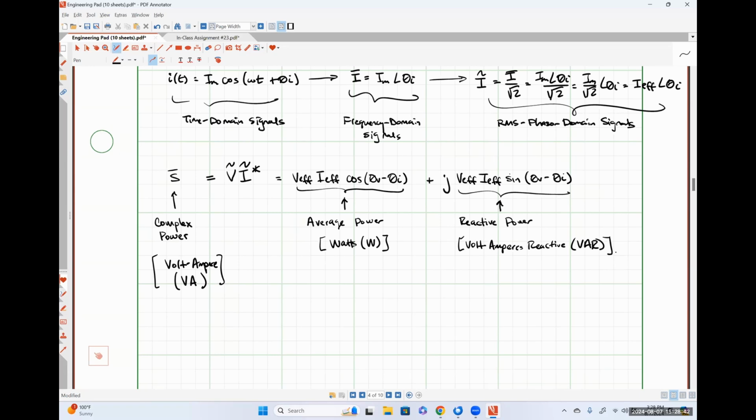I believe I mentioned a couple of days ago when somebody had asked a question about brownouts and all of that kind of stuff, or when you see your lights dim in your home or something like that. That typically happens when there's not enough reactive power in the system to help the grid as a whole ride out some sort of fluctuation. Okay, so that's the kind of thing that you might see.